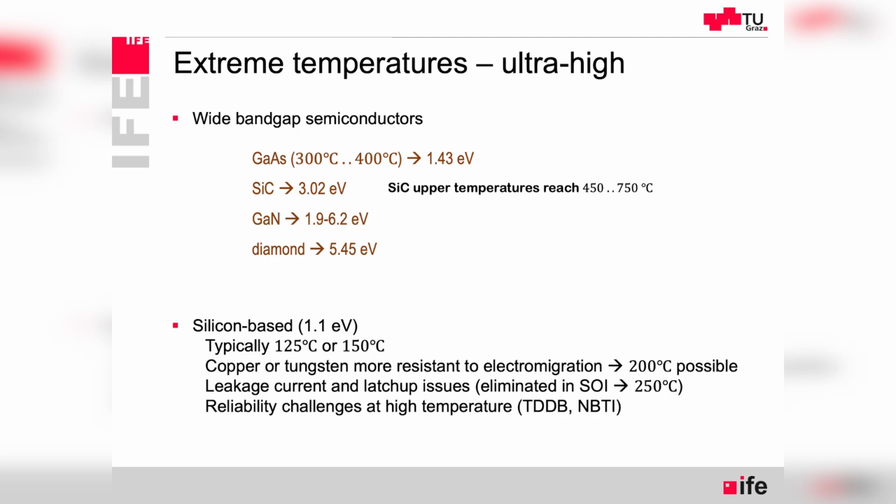The numbers I'm giving here are rather single examples, because in big-scale fabrication we would have challenges of time dependent dielectric breakdown and bias temperature instability. These are typical reliability topics, where after operation over a certain time, the devices don't work as initially when tested right at the start.